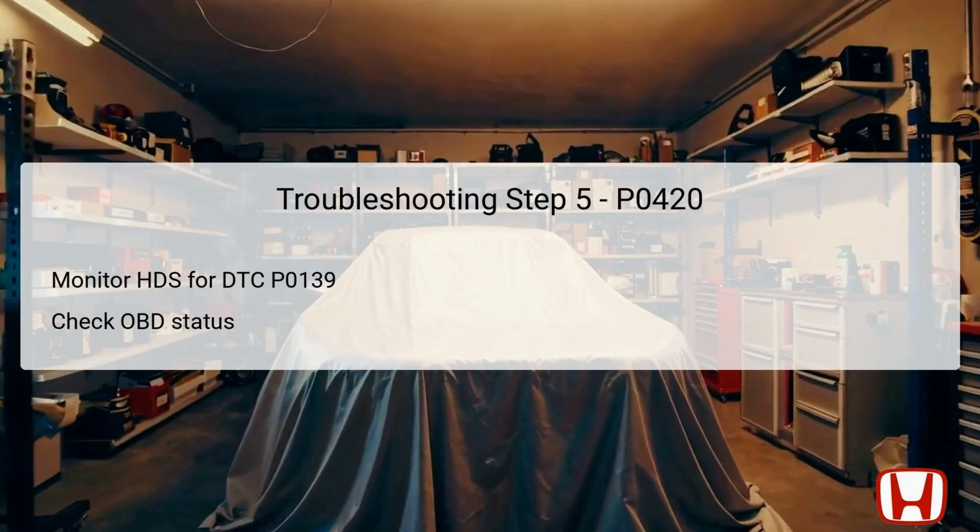This Diagnostic Trouble Code specifically relates to the secondary HO2S and indicates that there may be an issue with that sensor's performance or effectiveness. Checking the OBD, or onboard diagnostics, status for this code is paramount, as it can help pinpoint whether the problem lies solely with the catalytic converter or if the HO2S is malfunctioning, causing the PCM to erroneously trigger DTC P0420.